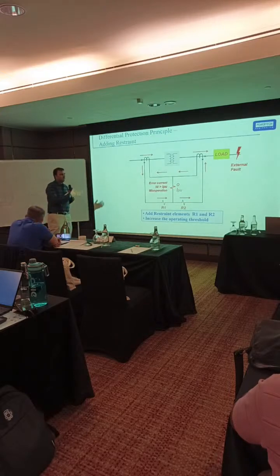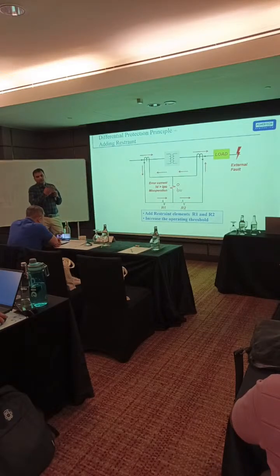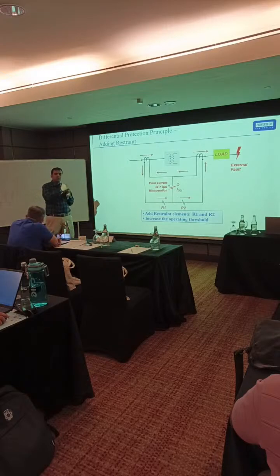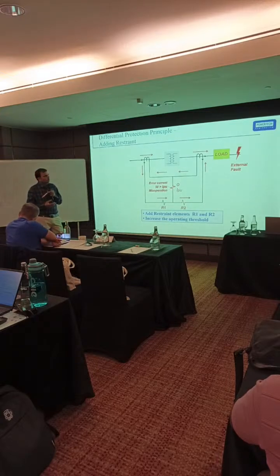What we have explained is just the errors, how much error it creates. So the slope sometimes depends on the relay setting of the particular manufacturer. All manufacturers have a different restraining current calculation method. So based on that, the relay setting system.